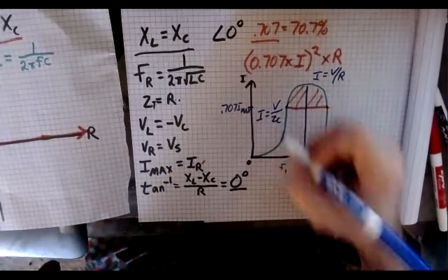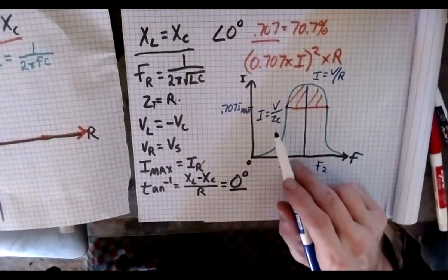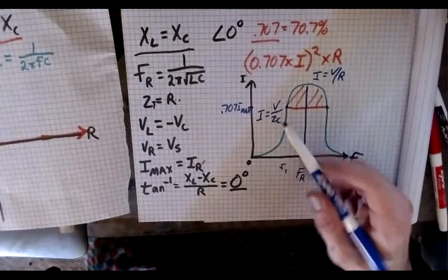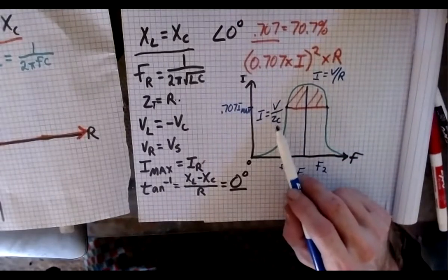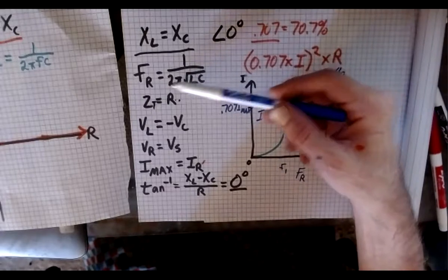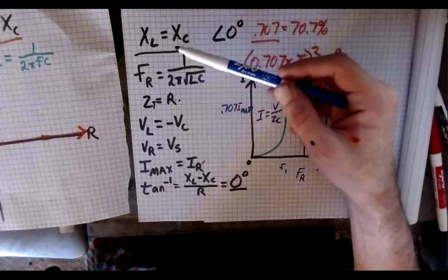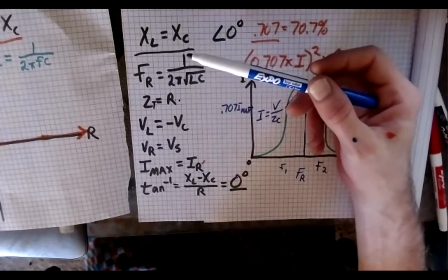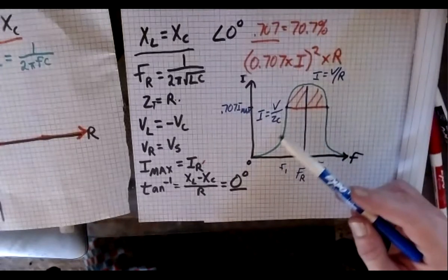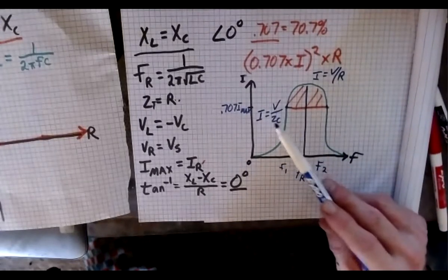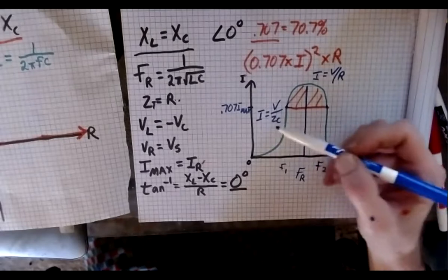and Ohm's law. So as we start going this way, the circuit becomes more capacitive because it's right in there, right? If we look at the X_C formula, 1 over 2 pi f C, as that frequency starts to fall, the circuit starts to become more capacitive in nature.